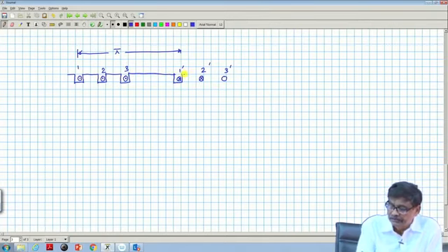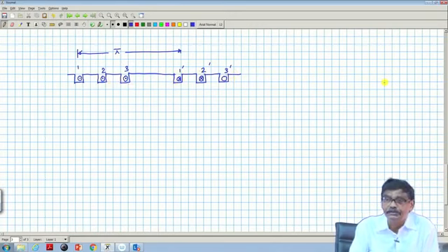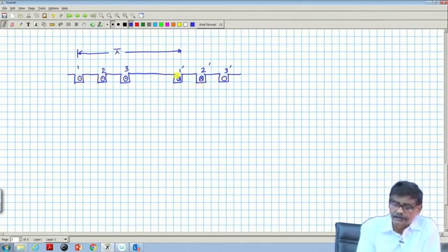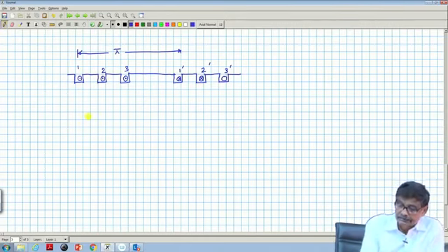Suppose the armature is having only 3 coils like this. If it is like this, then after this much length here once again 1, 2, 3 you will see, because you have a developed diagram of the machine. Now, the question is what will be the MMF distribution? Consider one coil at a time. For example, 1 and 1 dashed, it will be like this.